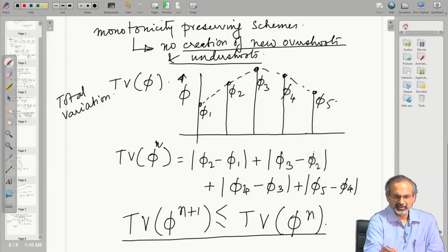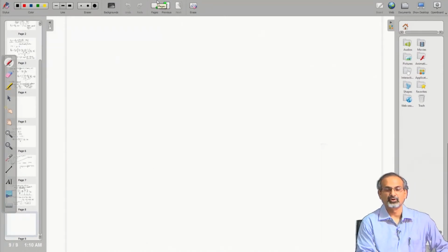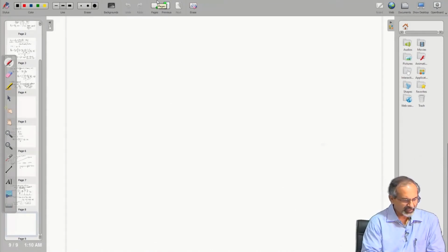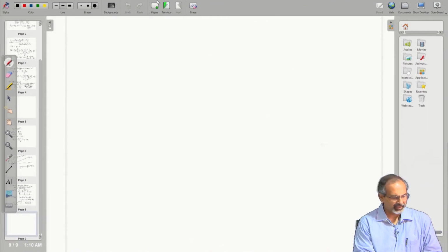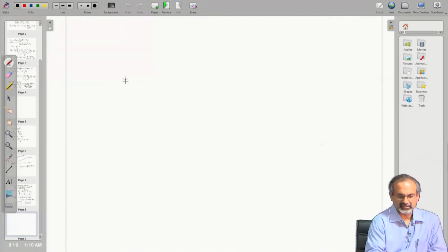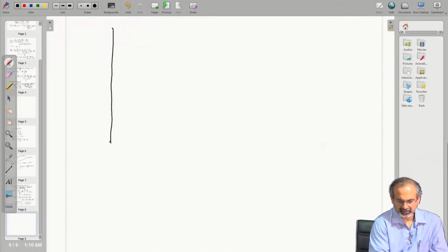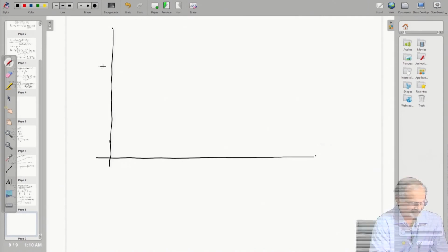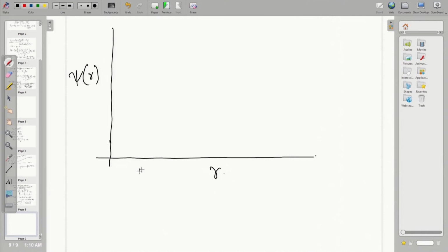So, this was a very important concept in developing schemes devoid of oscillations, but still retaining higher order accuracy. The main aim was to keep second order accuracy as the target and build schemes which are devoid of oscillations. So, we go back to the phi r plot once more, or rather the psi r plot once more, and we try to look at those regions carefully. We will shade a certain region now, which is going to be a very important region for us.